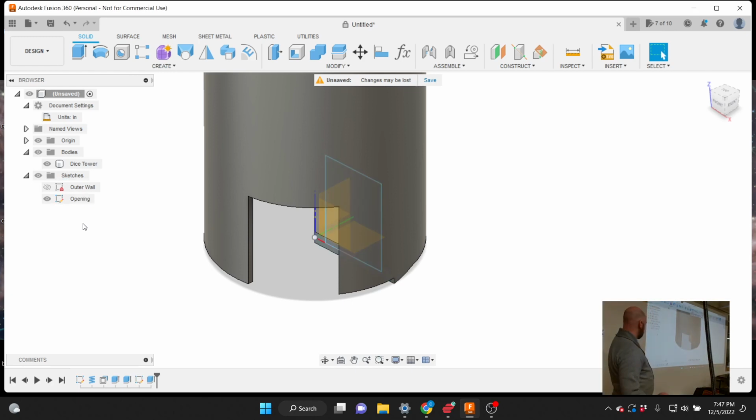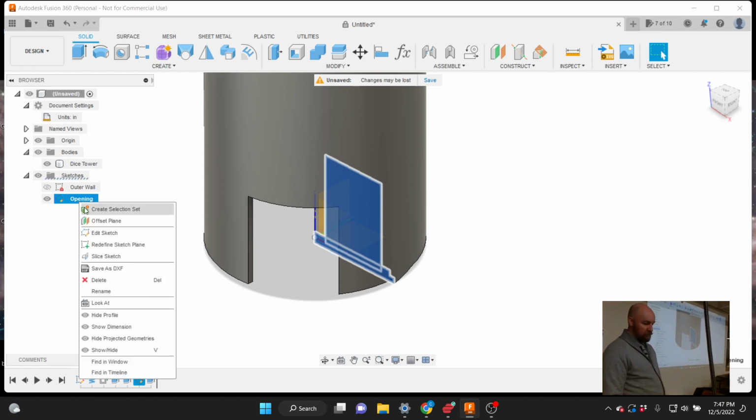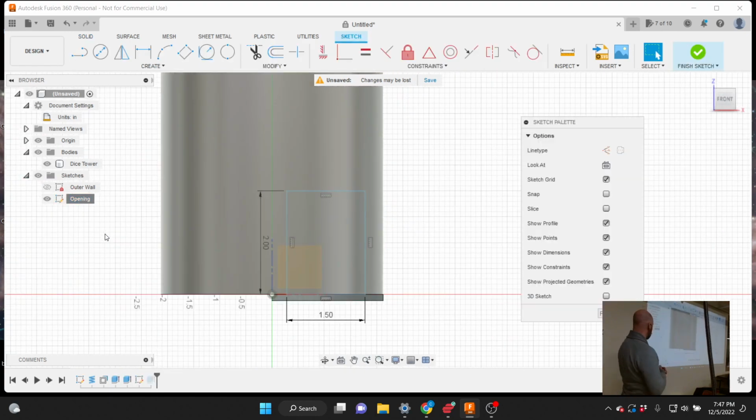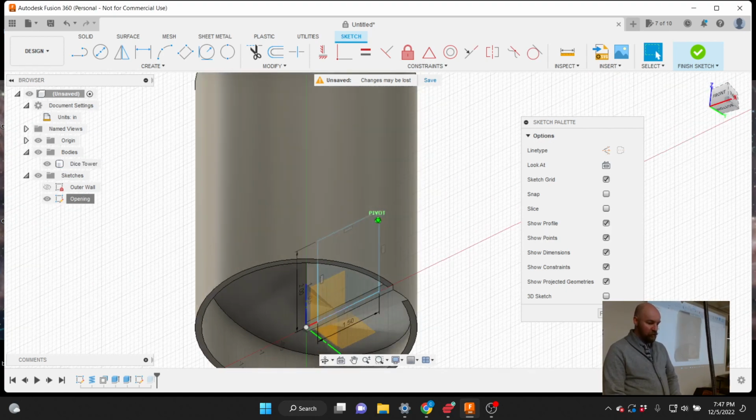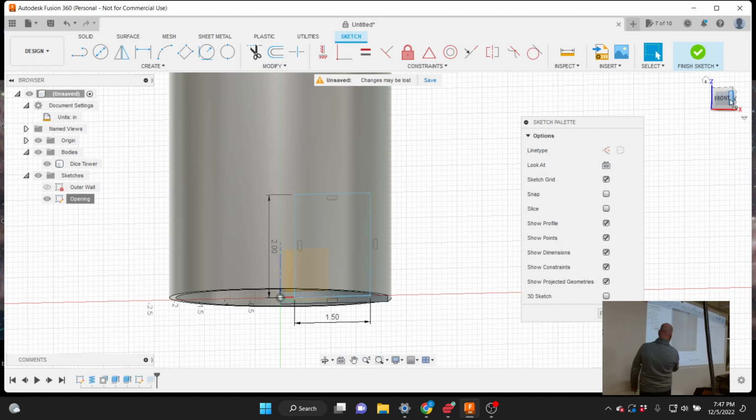If I right click on this opening sketch, I can go back in time and edit that sketch. You'll see now we no longer have an actual opening because I have gone back in time in my timeline. It's kind of grayed out, and now I'm back at the place where I was making that sketch.